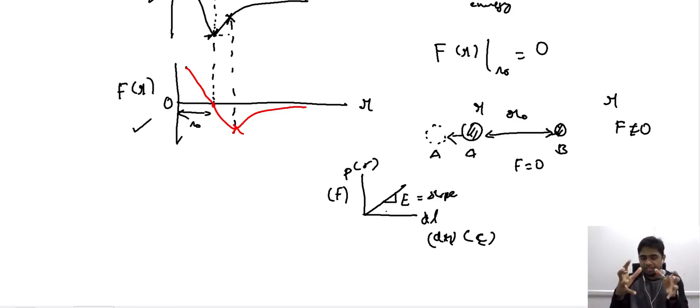Irrespective of the parameters that we use to describe the mechanical behavior of the material, the trend remains the same. Therefore, for load, elongation and also for stress and strain, the elastic region remains linear. And the slope of this linear region is the Young's modulus.